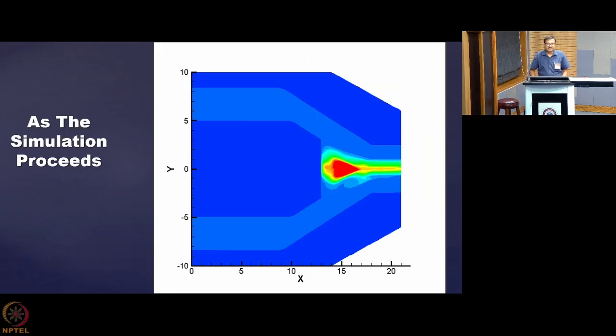So that is how the nozzle design affects the scenario in a much more prominent way compared to what happened when you were just changing the gas. Changing the device geometry has an immense impact on the plasma jet characteristics coming out, because it is able to shape the electromagnetic body forces in a significant way, and that is how it shapes the behavior of a current-carrying fluid like a plasma jet.